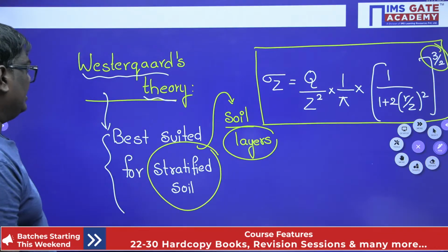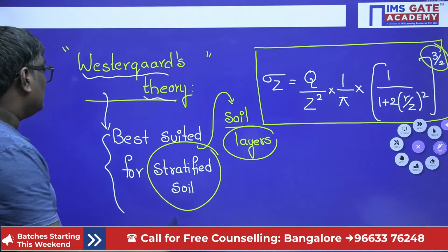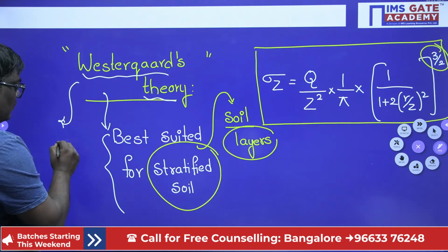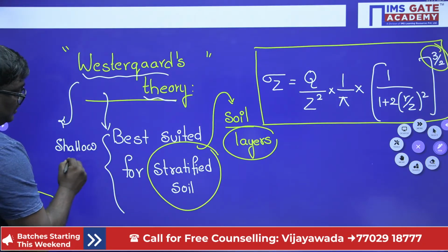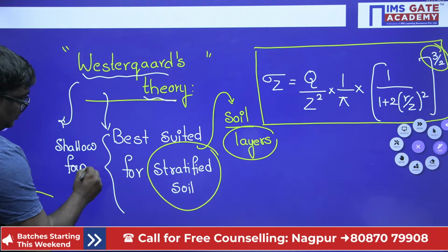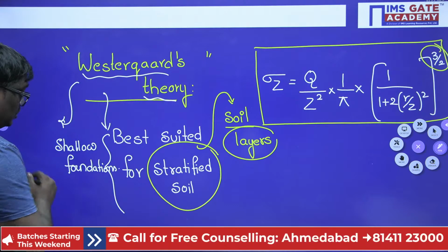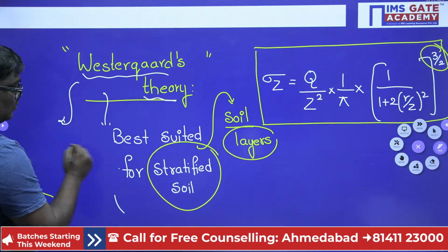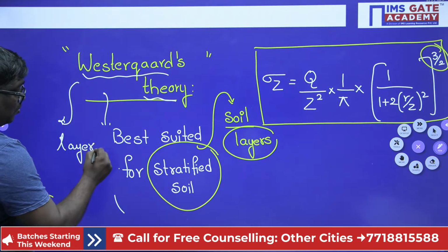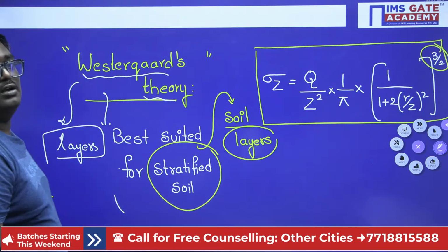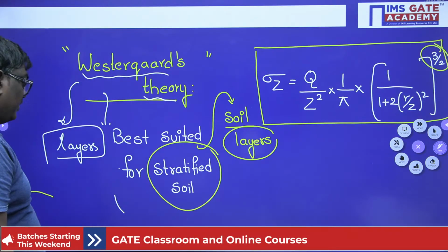I hope you are clear. Boussinesq's theory is best suited for shallow foundations, and Westergaard's theory is best suited for stratified soil, or soil which is in the form of layers.